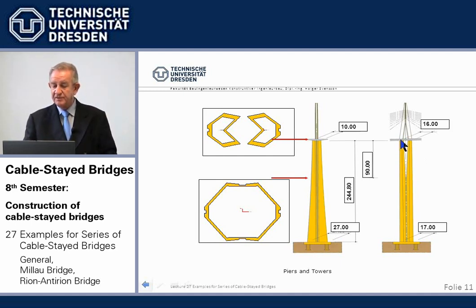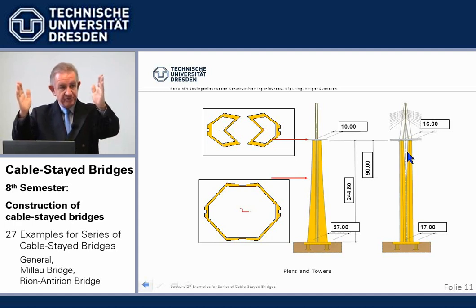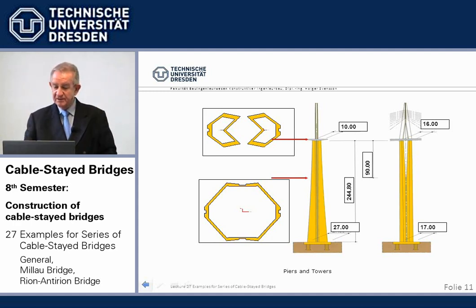Well, we receive the spread tower legs by spread pier legs. You see here the pier has a slot, a cut in between, and so the force couple from here goes directly into a force couple here, which is again very stiff.